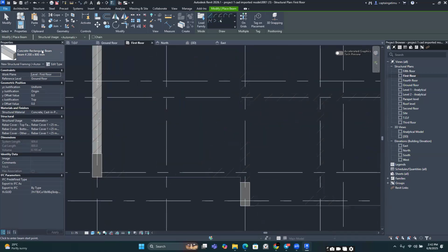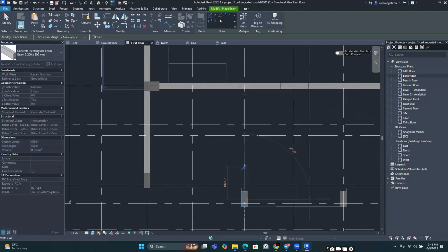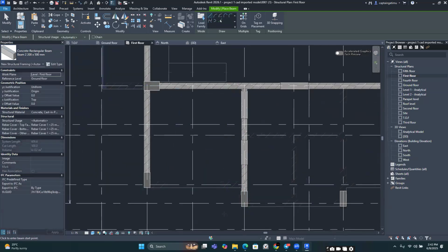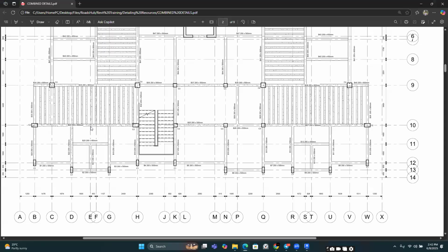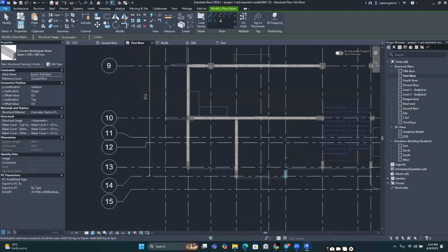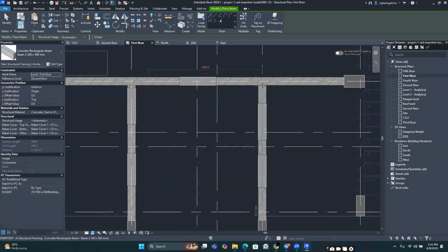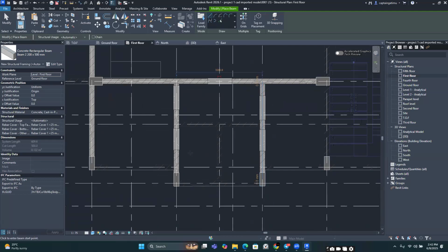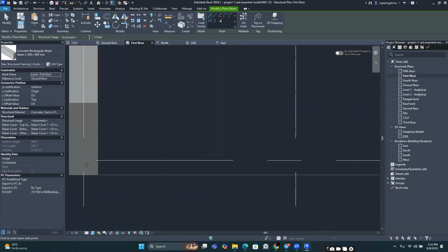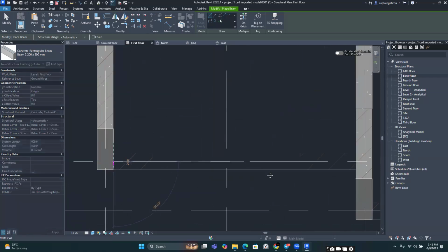Again, here we have 200 by 500 from here to these points. Okay, it's just that I've done this a couple of times. I have the dimensions probably in my head, so I know where they are. So you confirm using this PDF and place them. Okay, so placing them is easy. Just draw them on the areas where you need them or where they have been placed. Place the correct cross section. So here we have 200 by 500.